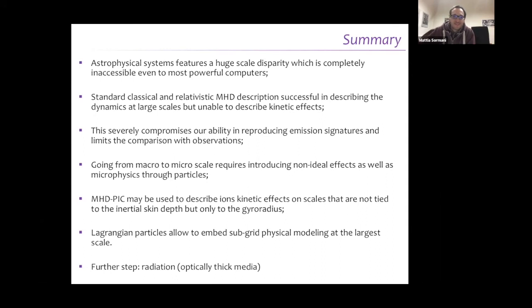There are advantages and disadvantages. A moving grid code will allow you to access an almost Lagrangian-like formulation, so the numerical dissipation is very much reduced, which is a desirable effect. However, there are complications due to the grid structure generation. Dealing with conservation of the solenoidal constraint of the magnetic field is a mess, because everything is skewed, so it's hard to conserve that. And then you have issues with boundary conditions. I don't know, it's difficult to say at this point.